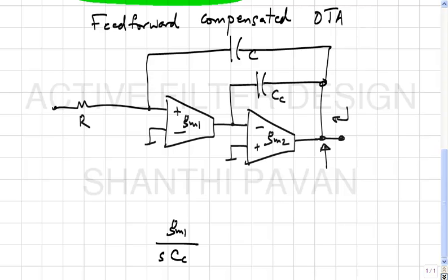Of course, the expressions become extremely messy the moment you add capacitors here, here, perhaps here also, and do the maths to get the exact transfer function of this integrator with finite GM1, GM2, C1, C2, C3 and so on. If you need to do it, you can always do it; that is not a big deal. The only thing I am trying to do here is to give some intuition about what kinds of improvements one can expect when one implements the transconductor, the OTA, this way, correct.